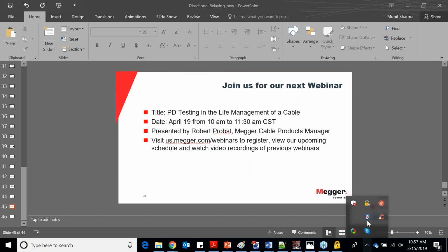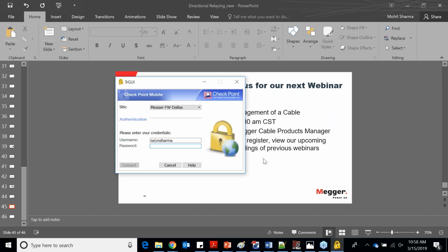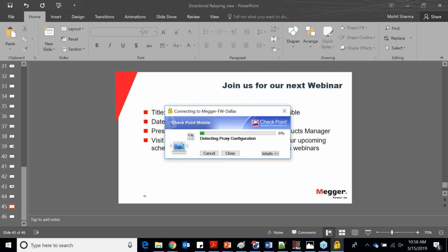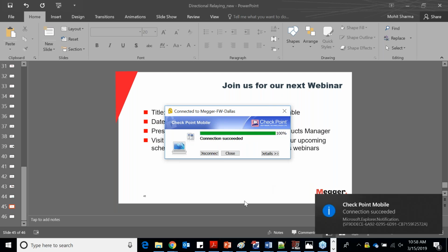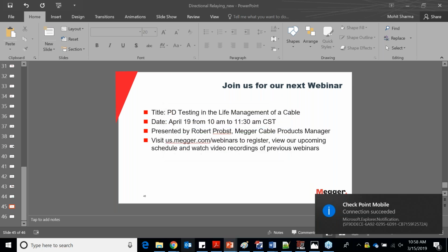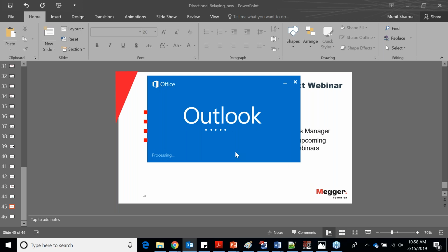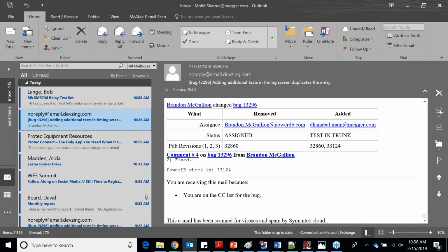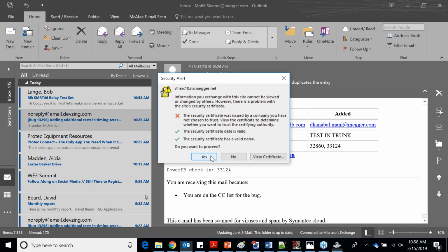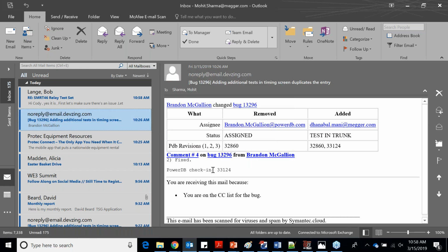First one we have on the list is: on a high resistance grounded system, the capacitance current is the design factor, and it flows from line to ground and is balanced. But during a single line to ground fault on the network, this capacitance current changes its direction and flows from ground to line, because the total current now is the vector addition of NGR current plus this reverse capacitive current. Is there any way that we can have ground directional protection 67N using a zero sequence CT?